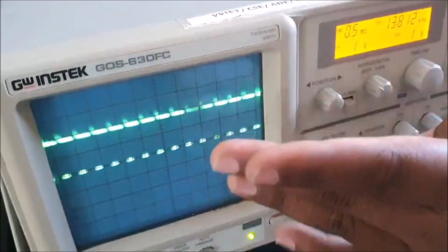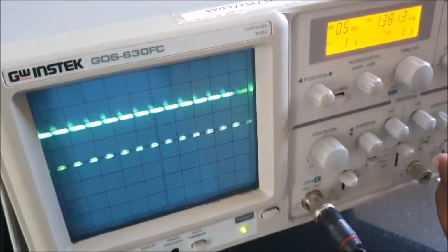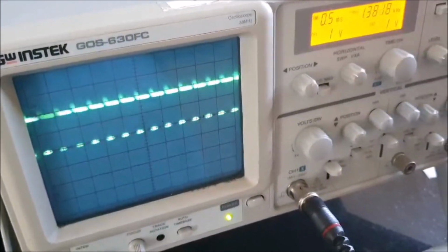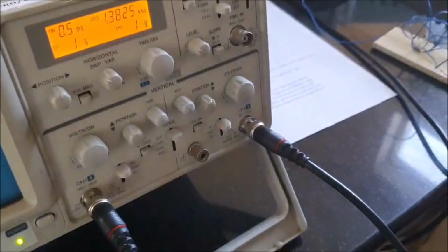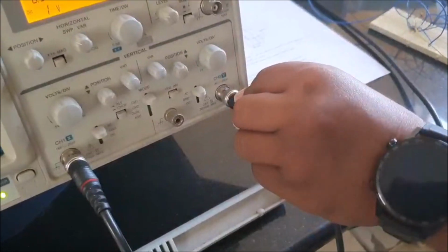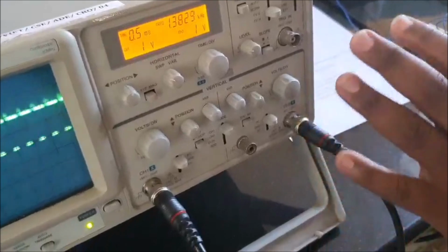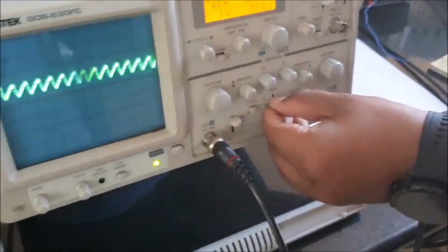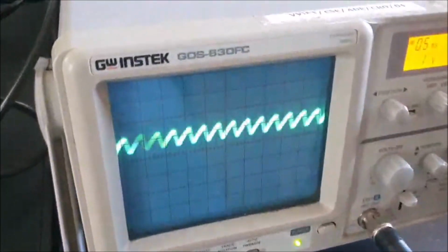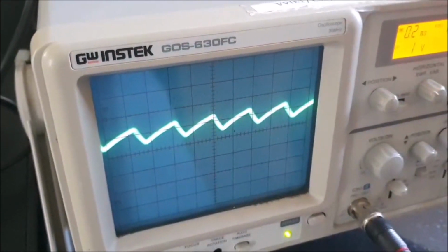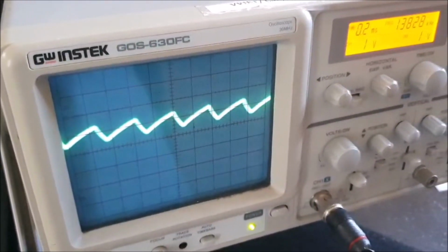One is the T on, the below one is called the T off. And the positive of the other channel on the CRO is connected to the 6th pin, where if I need to get the capacitor waveform, the capacitor waveform will be a Sawtooth. So this is how this Sawtooth waveform looks like. So this is the capacitor waveform.